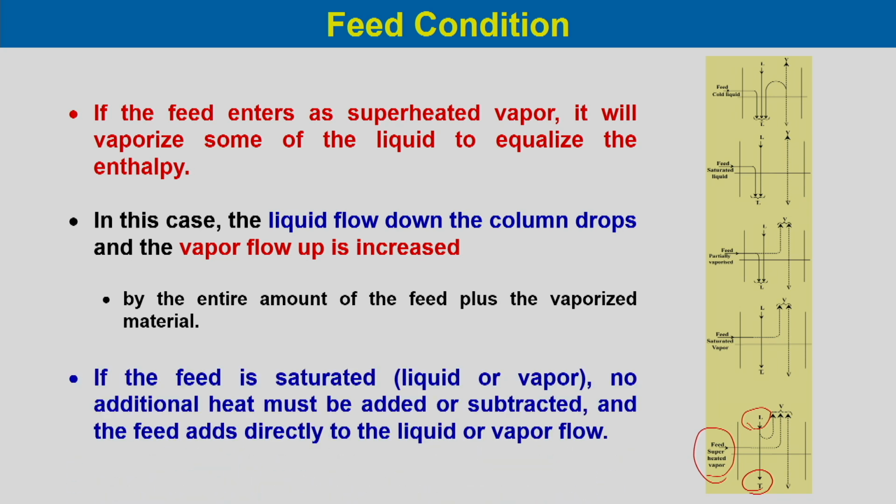If the feed is saturated liquid or vapor, no additional heat must be added or subtracted, and the feed adds directly to the liquid or vapor flows. So, if you take saturated vapor, basically this vapor need not heat the liquid which is coming down.